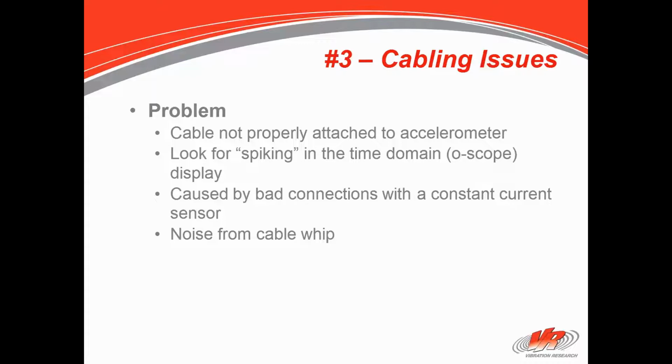The electronics which run the accelerometer, and which may also supply power for the TEDS chip inside, provide it through the cable via that DC offset. Well, if the cable opens and closes, that's going to be a transient that comes right through the capacitor, and your controller is going to see it as a spike. It doesn't know whether it's a big G spike, like you dropped the accelerometer or had an impact event, or if the cable intermittently opened. So if the shaker is running some small acceleration, but you see a big spike on it, check your cables.